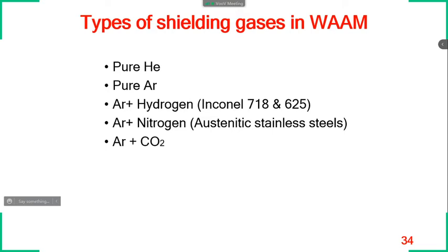In welding, generally helium is being used. Why is helium used? Wherever we want to achieve a greater depth of penetration, especially in the welded joint, we generally go for helium gas. Why does helium have that tendency? Because helium has a very high ionization potential as compared to argon. So for the same power, same voltage, if a GTAW torch is producing an arc,